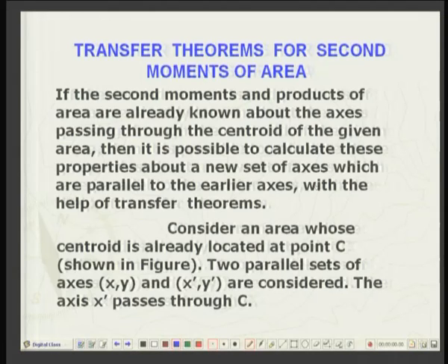Now, let us go to another very important part of this lesson, transfer theorems for second moment of an area. Suppose you know the second moments, that is Ixx, Iyy and Ixy about a given frame of reference, that is xy coordinates, z being perpendicular to the plane of the area.